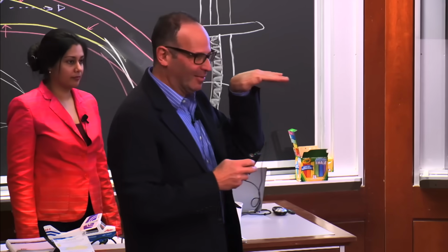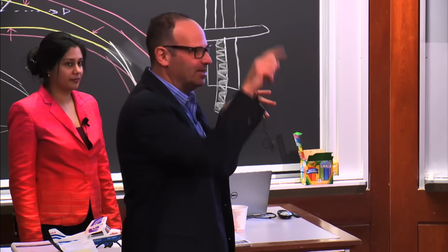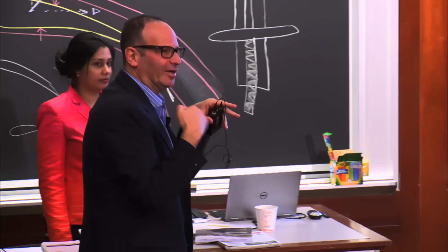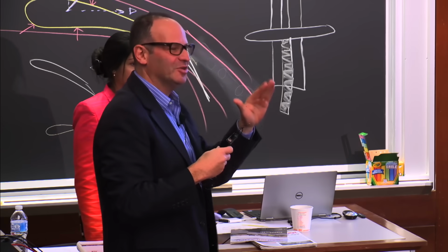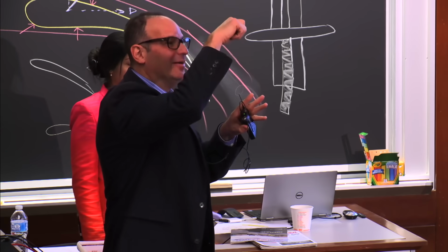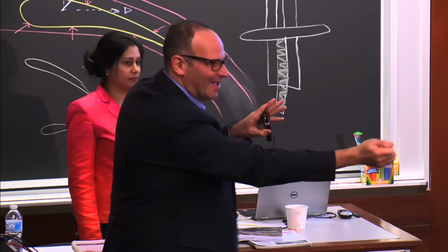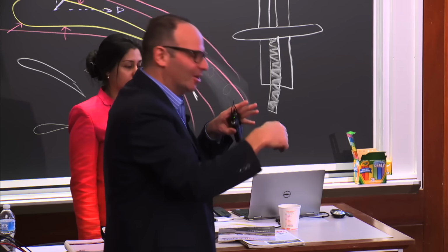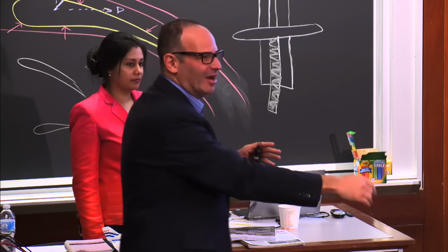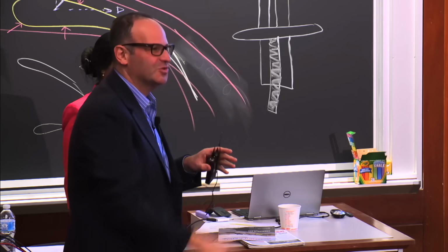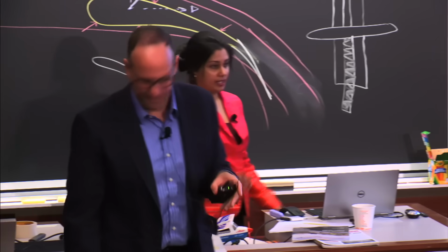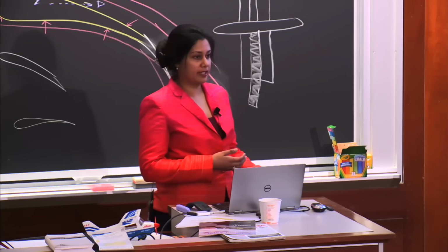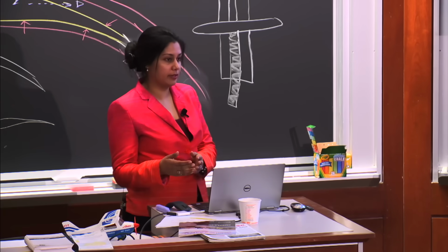If you think about it, when the airplane's level, the propeller is not moving relative to the oncoming wind. But if you tilt the airplane up, as the propeller goes down, it's actually advancing into the wind and getting a little bit of an efficiency boost that way. Whereas when it's coming up, it's going from the front of the airplane towards the back, so it's retreating. So what Philip's describing is why the right propeller blade is generating more thrust than the left propeller blade, which is what's moving the center of thrust.